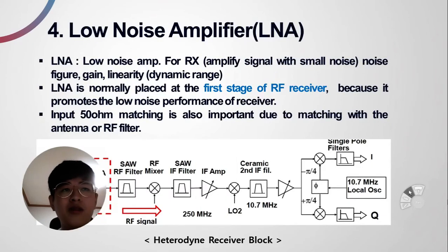When a signal comes through the antenna of the receiver, the signal strength is very small, so a large noise is very bad. For this purpose, an LNA should be used to minimize noise and amplify the signal. So the LNA is always in front of the receiver.